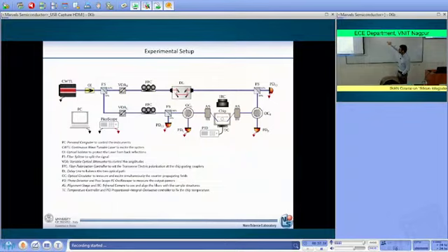But this light does not go along this line, it goes here. By using this photodiode, we can measure the light that is reflected by the microring resonator. At the same time, the light that is transmitted by the microring resonator reaches this other optical coupler, goes to port 3, and is measured by this photodiode.